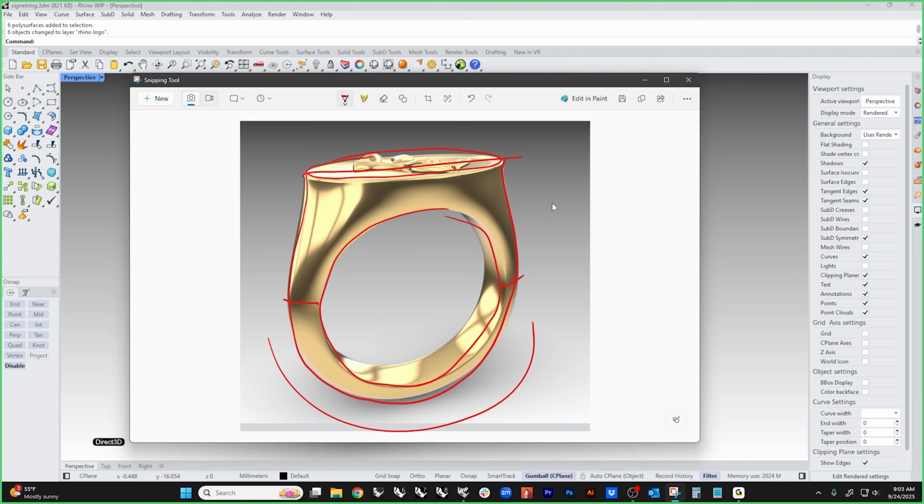This is easy. This is just a two rail sweep, right? So we know that. That's easy. This is just a shape, and we're just going to wing it around a couple of curves. There's a curve here and a curve here, so that's easy. We've got just a planar shape up here, so we can just make a planar shape. Then we say, okay, well, we've got a curve from here to here, so we're going to draw this curve, and we're going to draw that curve. And then I've got a curve from here to here, so I'm going to draw that over there.